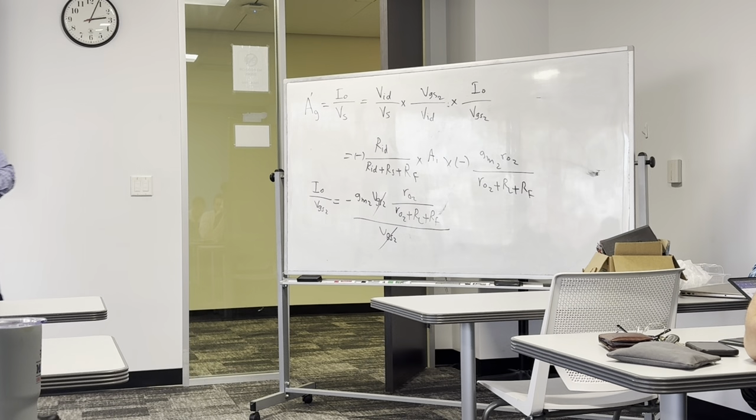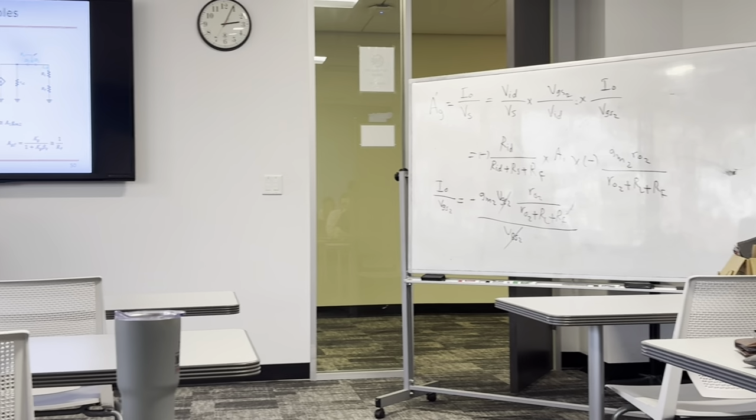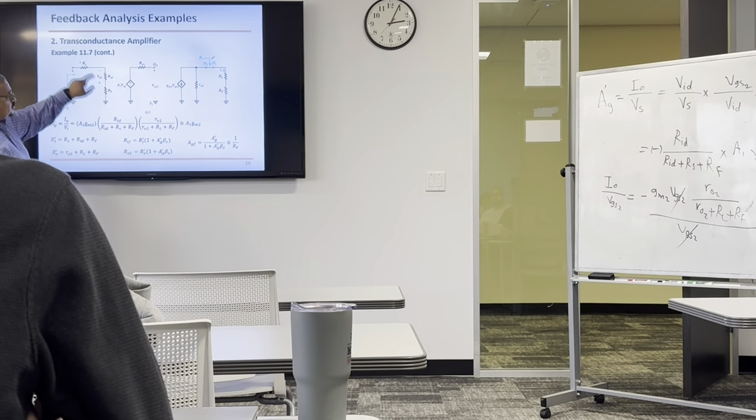See again, and I don't think this is difficult now, right? We practice. This is what you missed in chapter 7, how to analyze a circuit like this. So we can combine A1 and GM2 as constants together. This voltage divider, this voltage divider. Now, to approximate this equation, you can assume that Ri input differential is much larger than these two.